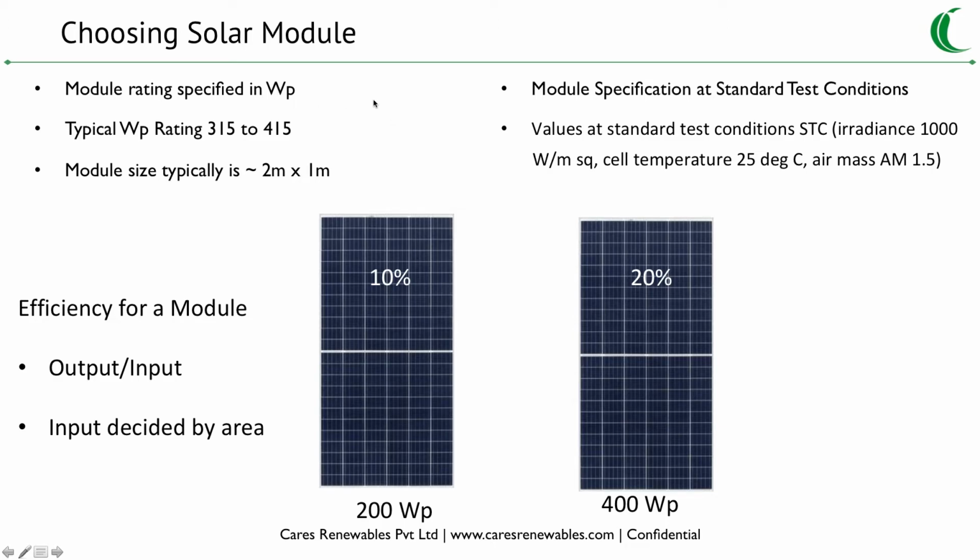And I'm not sure whether you recall me speaking about solar not being a constant source. So it's called watt peak because of the same reason, because it's the peak power which the panel can deliver. So it's not like a generator where you put a 100 watt generator and you get 100 watt.